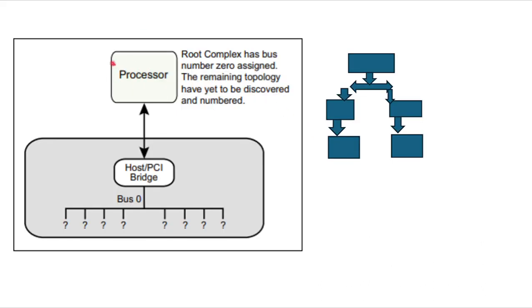See, this is the processor. The processor only knows the host bus. It is connected to bus 0. You don't know how many components are connected below, or what those components are. Let's consider our software has not configured any devices. What will happen? Let's see here.